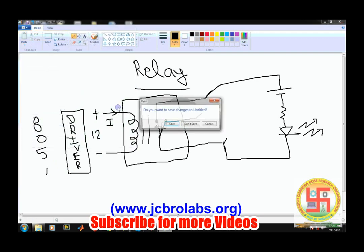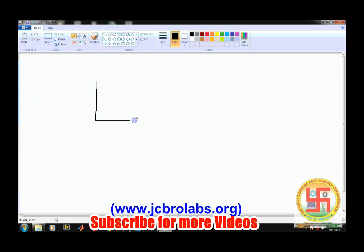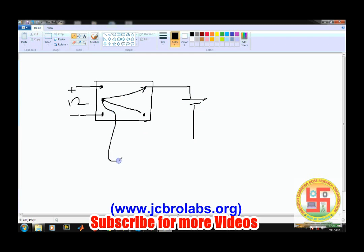There are several kinds of relays. The relay which we are using has 5 pins, and its back diagram is like this. We have one pin here, another pin here, and the next pin here, and we have 2 pins here. Because the relay can come in different forms, we need to understand which pins are connected to each other. For this relay, we need to apply the positive voltage at these 2 pins, and normally this pin is connected to this one, and as soon as we apply a power supply here, this pin connects to this particular pin. So for making a circuit, we will connect a power supply here and here.